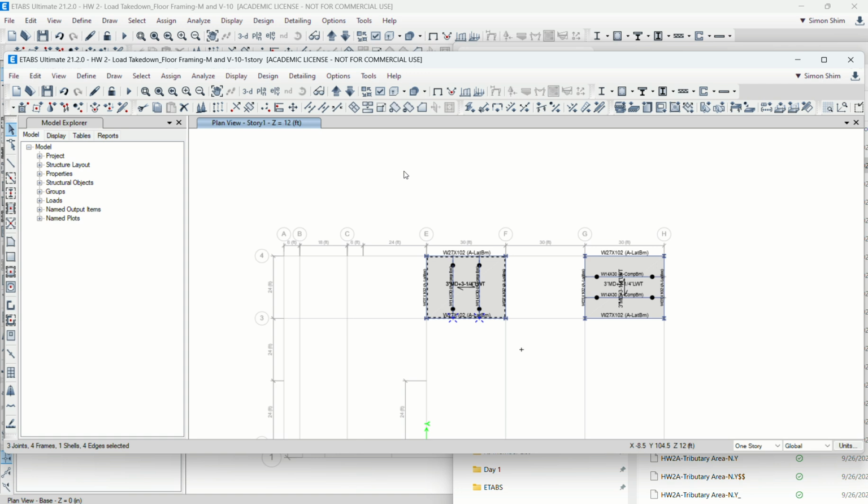In an office environment, you want a relatively long, big space, like co-working space, right? So I gave you 30 feet in this example. The span could typically be a little more, 40, 45 feet, sometimes more than that.